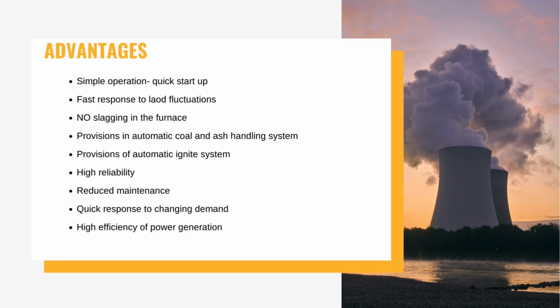No slagging in the furnace, no soot blowing in FBC boilers. Volatilization of alkali components in ash does not take place and the ash is non-sticky. This means that there is no slagging or soot blowing.